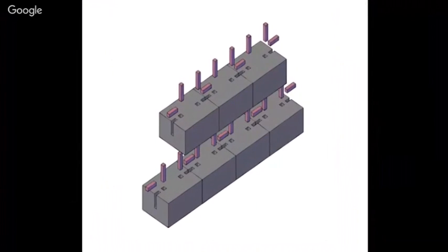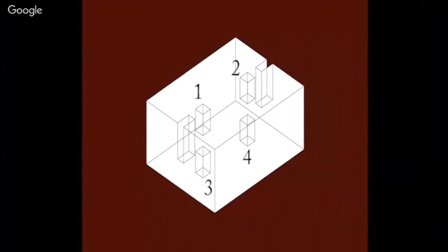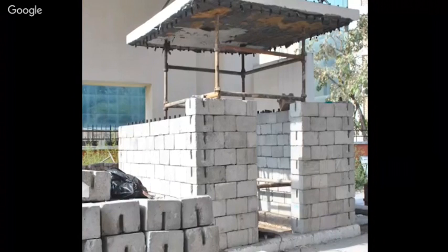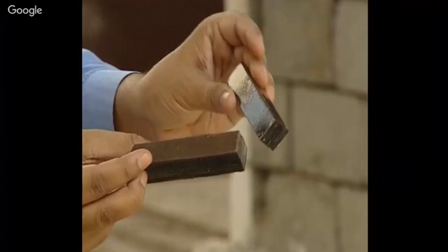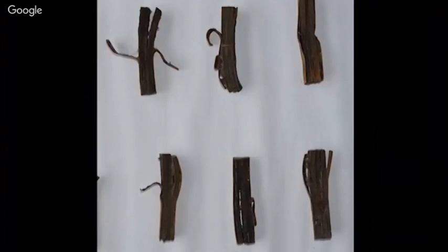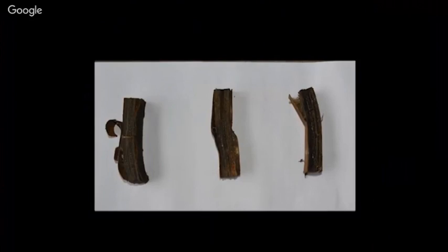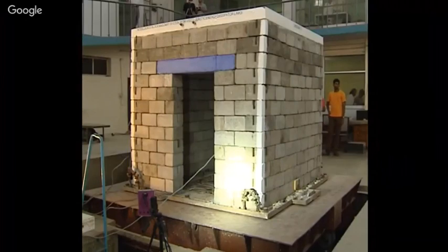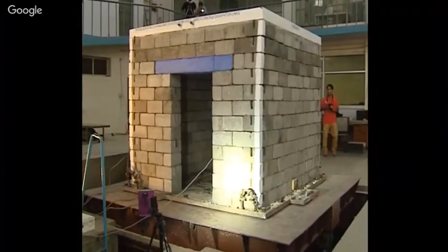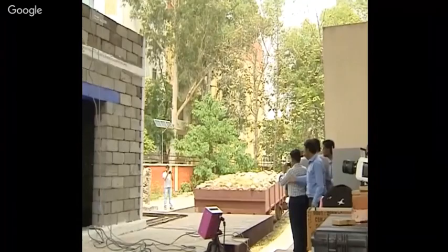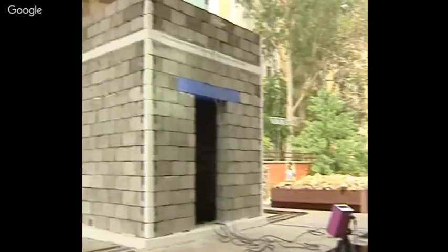Four vertical grooves have been provided to restrict translation and two horizontal grooves to restrict rotation under severe earthquake loading. The strength of the concrete blocks was kept much higher than the viscoelastic links, through the yielding of low-strength viscoelastic links and friction between the concrete blocks. The developed technology was then tested under severe conditions on shake table and shock table test facility by simulating artificial earthquake excitations.